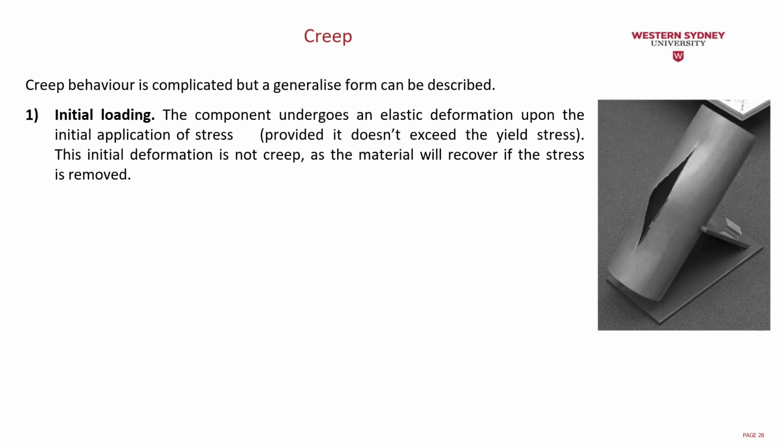The creep behavior is complicated, but the generalized form can be described. We first have the initial loading, where the component undergoes an elastic deformation upon the initial application of the stress, provided it doesn't exceed the yield stress. This initial deformation is not creep, as the material will recover if the stress is removed.